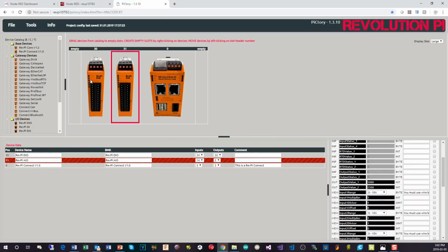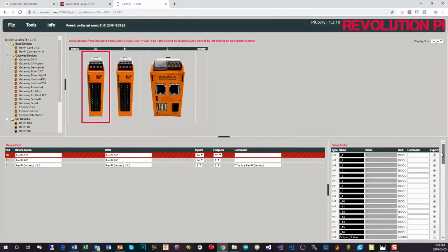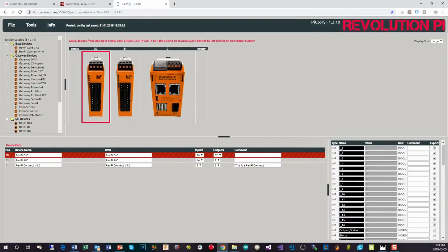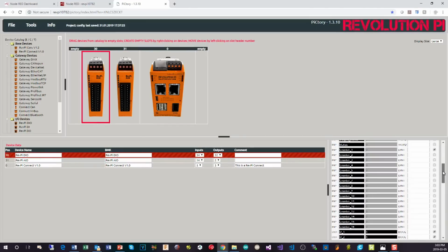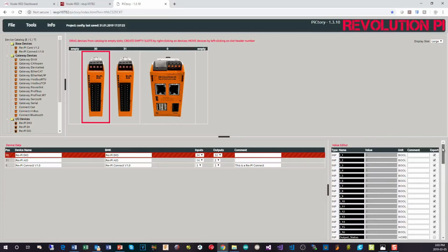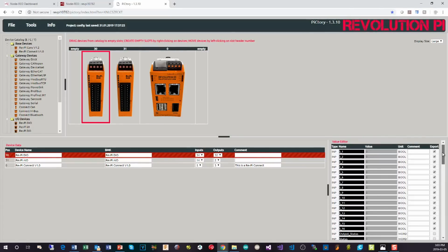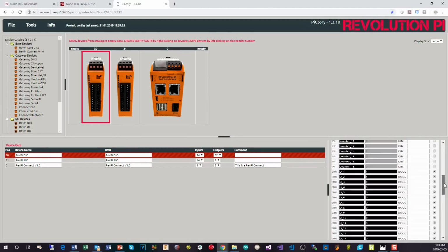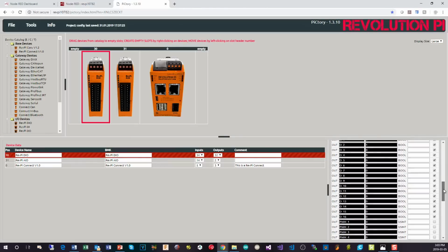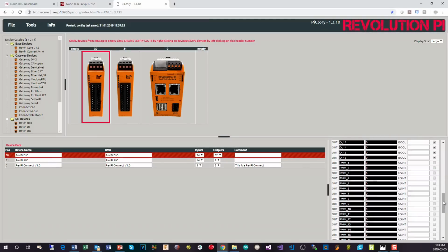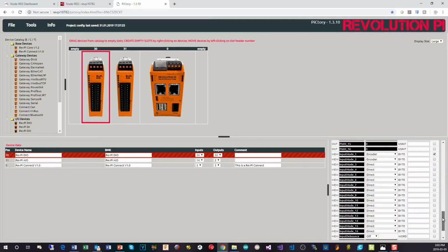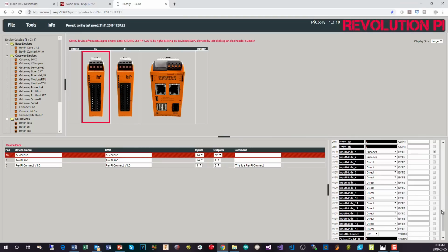For the digital I/O, it's the same story, but obviously you can see here that the naming convention is slightly different. We have counters that you can set up. We've got the inputs themselves, and this is the name of them. We have a number of counters, up to 16 of them, which matches the potential inputs. Now we only have, I think, 14 in and 14 out because it's an I/O module, not just an input or an output module. And then we have the outputs, so they're numbered from 1 through to 16. We then have things like PWM. Then we have the configuration part for these.